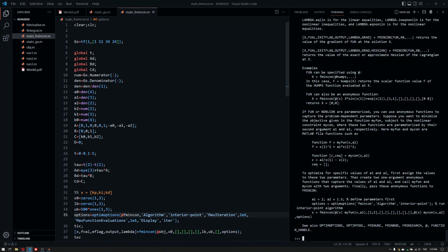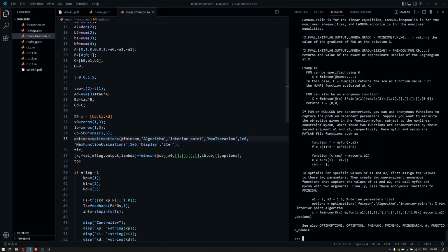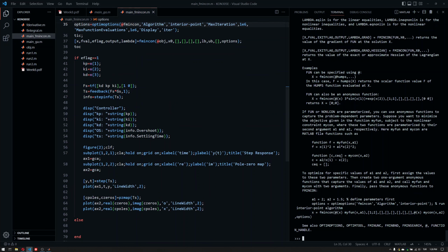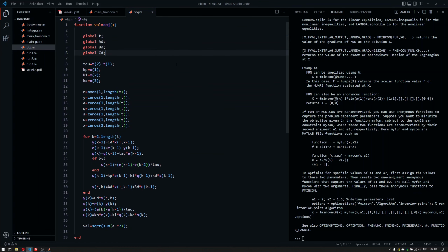But what we've done today is we've just used the zero order hold methods in order to solve a differential equation that represents a transfer function. And we've used basically the idea of taking a numerical integral and derivative in order to implement our PID controller. We have embedded our PID controller into the differential equation solving methods. Here an objective function, obj.m, and you can see we have a nice little function that gets rid of all the necessary stuff. And as I've already told you, you can just do this whole thing in C.